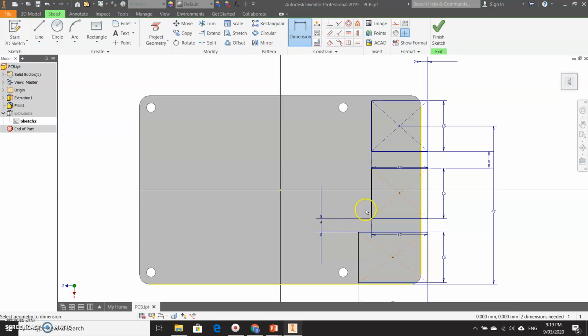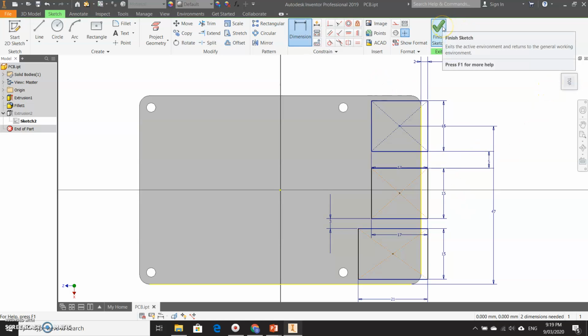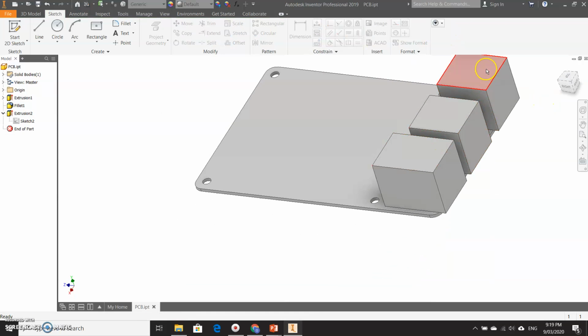Press OK and go to, oh sorry, that's a wee bit much by the looks of it. Let's turn it back by about 3. Now you can double check these measurements on your own drawings. Okay, and we'll click on Finish Sketch. I see what's going on now. Right, Finish Sketch. Right, now then, so it's automatically updated those.